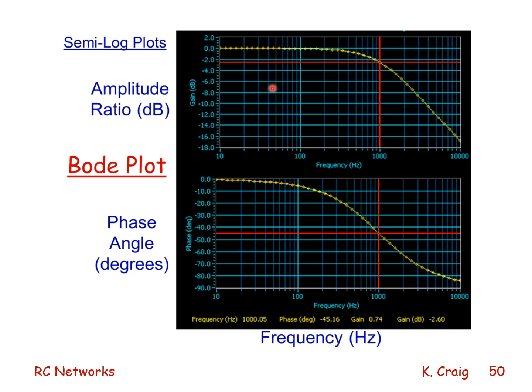There are such things as dynamic signal analyzers available, as there are digital oscilloscopes. But while an oscilloscope might cost a few thousand dollars, a dynamic signal analyzer costs $25,000. So this virtual Bode plotter is very, very useful and time-saving.